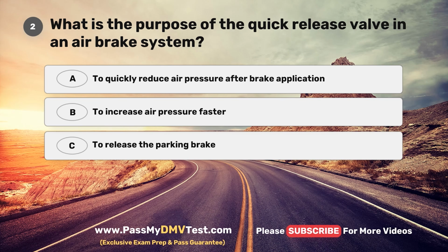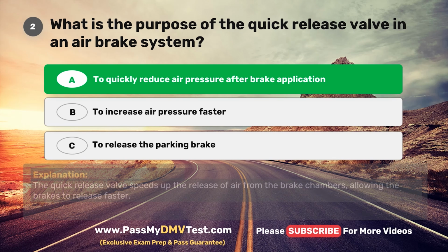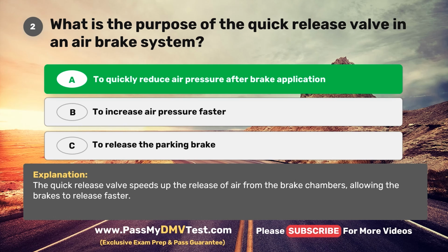Question 2. What is the purpose of the quick release valve in an air brake system? A. To quickly reduce air pressure after brake application. B. To increase air pressure faster. C. To release the parking brake. The correct answer is A. To quickly reduce air pressure after brake application. The quick release valve speeds up the release of air from the brake chambers, allowing the brakes to release faster.